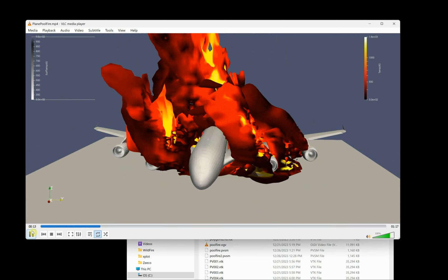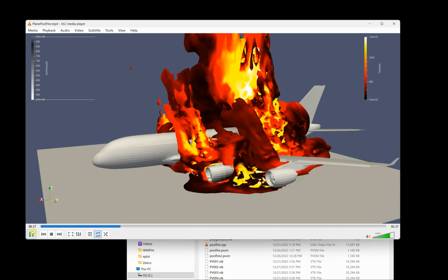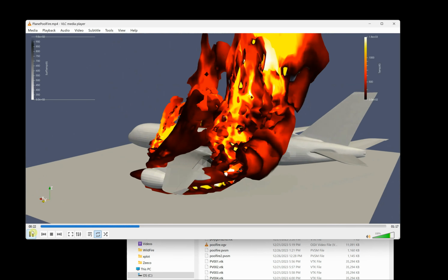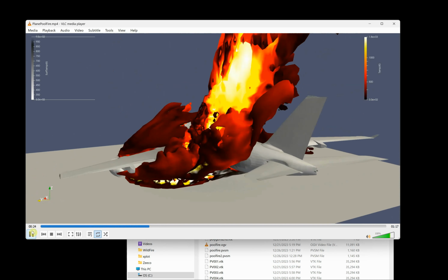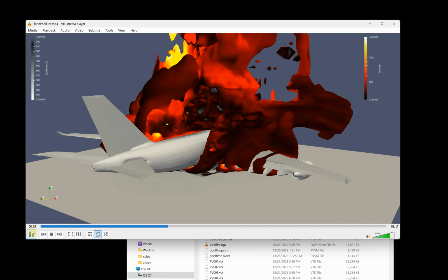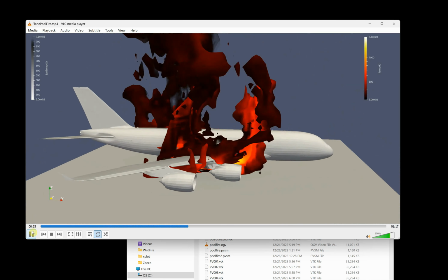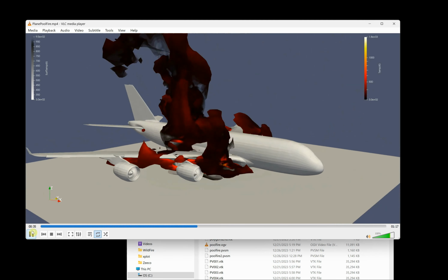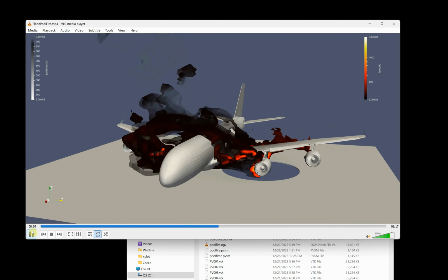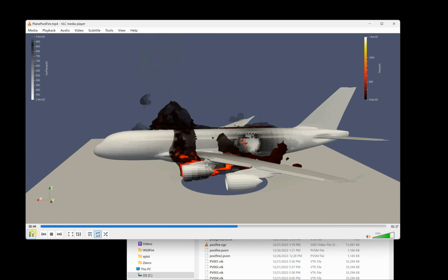And this first circle takes about 20 seconds. And if you might recall, the emissivity of the skin was 0.1, so the actual time scale for heat up is 10 times longer, so about 200 seconds per rotation. And for the second rotation, the fuel injection from the pool was turned off, and you can see the smoke is dissipating with a little bit of residual flames gathered around the engine, which haven't blown in.